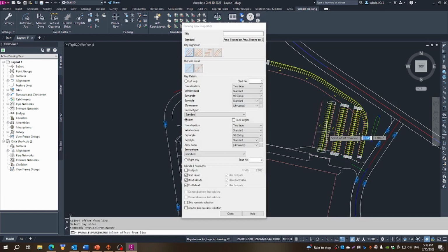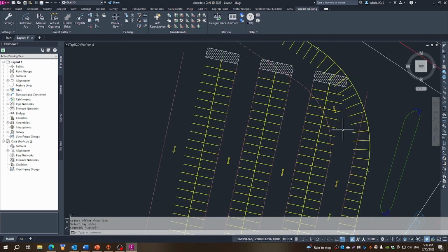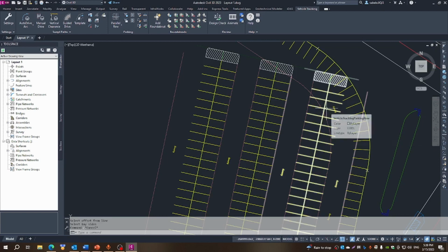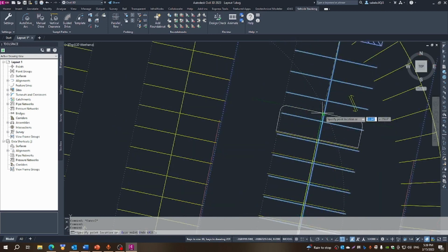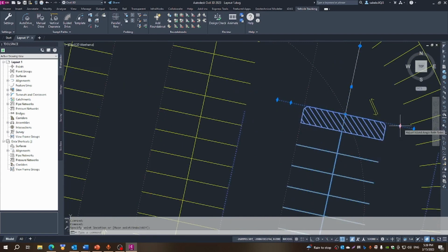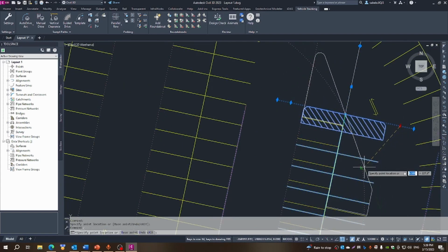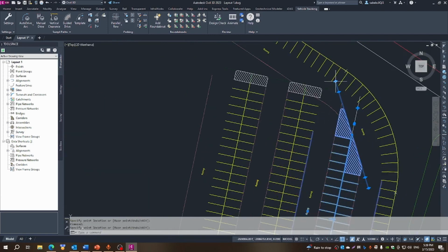We will put another one there. Okay, let's leave this now. We're now going to use the intelligent grips to alter these new parking rows to meet the area that we have to work with in order to stay clear of the travelway. So if we do that, we can now use these grips and we bring that parking row to there, and we can swing these to about there.